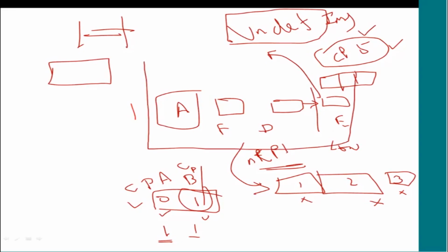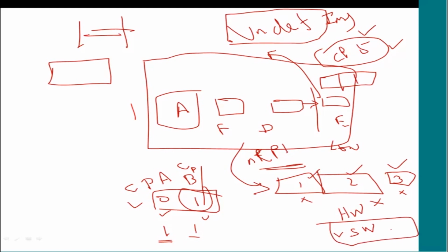As a system designer, I may decide to have a coprocessor in hardware, or I may decide to do a simulation of it in software. Suppose the floating point operations can be done in software also. So I may emulate it in software, and in that case it should be executed in the handler.